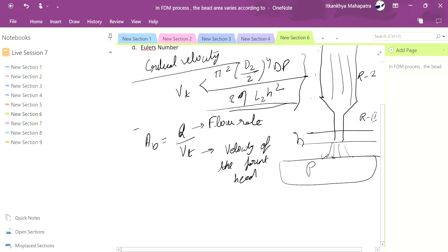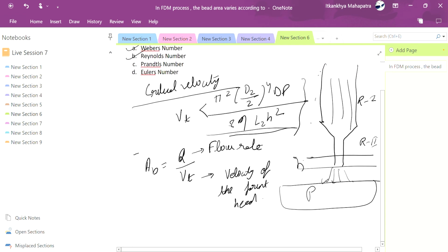After leaving the liquefier nozzle in a melt extrusion additive manufacturing process, the bead of polymer melt lands on the substrate or a previously printed bead of polymer. When it passes through the print nozzle we have a volumetric flow rate, and the cross-sectional area of the bead is inversely proportional to it.